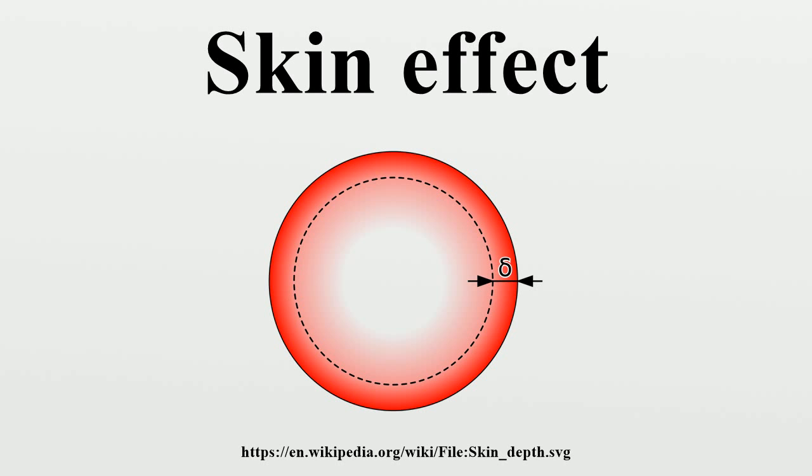Mitigation. A type of cable called Litz wire is used to mitigate the skin effect for frequencies of a few kilohertz to about 1 megahertz. It consists of a number of insulated wire strands woven together in a carefully designed pattern, so that the overall magnetic field acts equally on all the wires and causes the total current to be distributed equally among them, with the skin effect having little effect on each of the thin strands. The bundle does not suffer the same increase in AC resistance that a solid conductor of the same cross-sectional area would due to the skin effect.